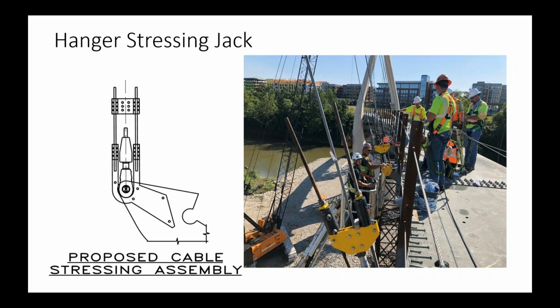One of the lessons learned here is it's advisable to have spares. It's a bit time consuming to install this jacking device and get it on the cables and ready to go. Once it's on there, it only takes a few seconds to stress it, but installing it and getting it lined up is a time-consuming process.